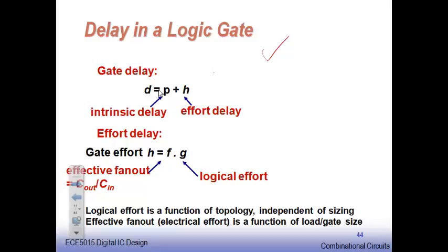Inherently, you have the delay incurred due to driving its own intrinsic load, and the delay incurred due to driving the additional load. Therefore, I have my gate delay defined as the delay my circuit incurs due to the intrinsic capacitances, and the effort delay. What gates I drive, how many such gates I drive.